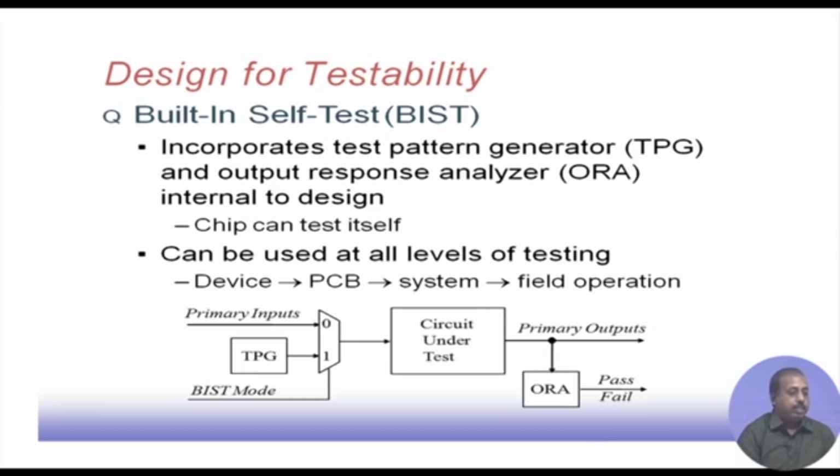Also, there are built-in self-test structures. Here, for the circuit under test, we do not apply test patterns from outside. In the circuit itself we have a test pattern generator and a response analyzer integrated. From outside it is just told to start testing now. Accordingly the test pattern generator goes on generating the test patterns, which are applied to the circuit. The responses we get are compressed at the output response analyzer, and when all the patterns have been applied, it declares whether the circuit passes or fails the test. This is very useful, because from outside I do not have to apply any test vector. There is no question of ATE, automated test equipment, transferring the patterns and all that.